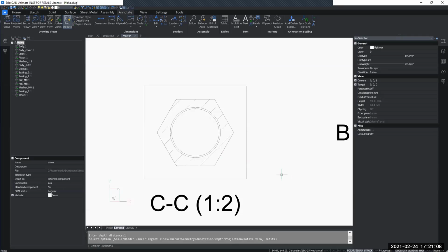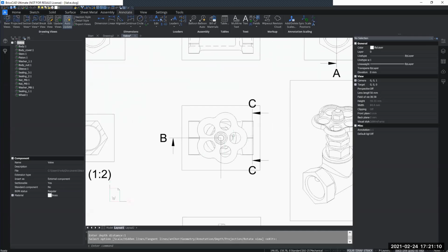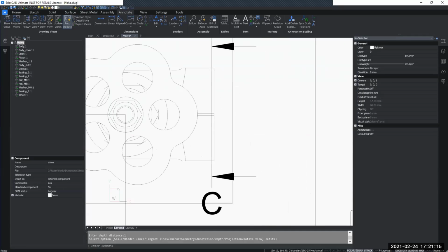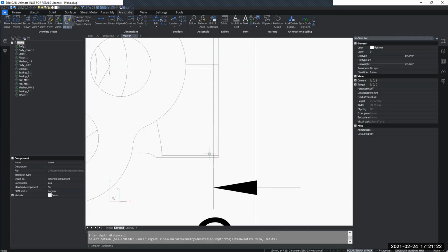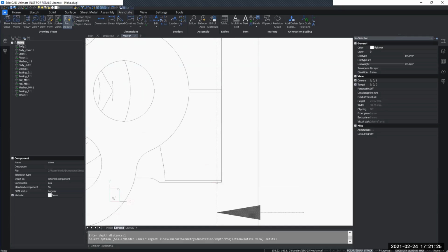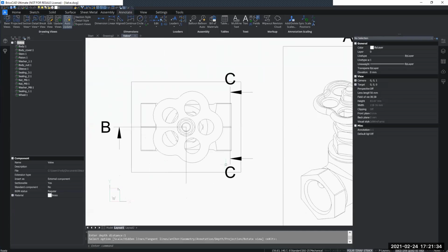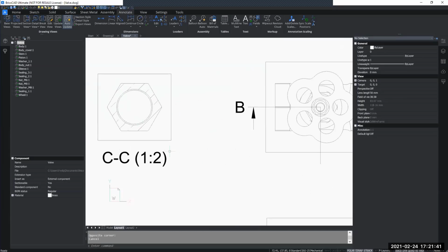past my section line. So the way it works is that the face we see here is the section line, and all of the material it keeps is only that 1 millimeter extra that I typed in. So it keeps the section line and then a 1 millimeter slab past that section line, and everything past that it disregards in that view. So everything past here, for example, is disregarded as it's not interesting in this specific view.